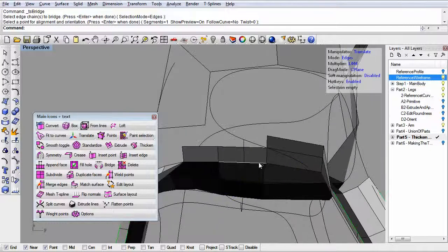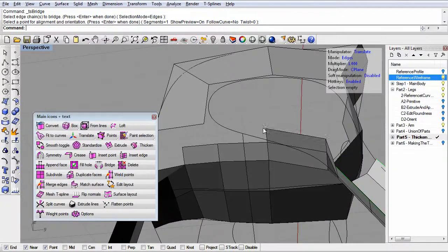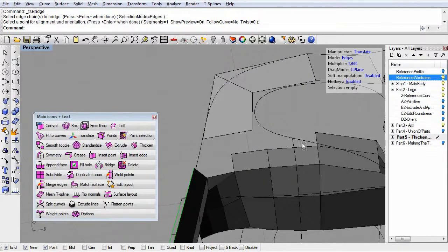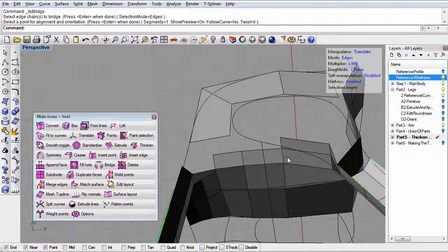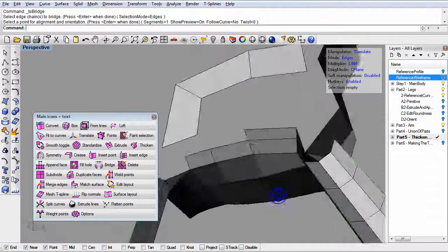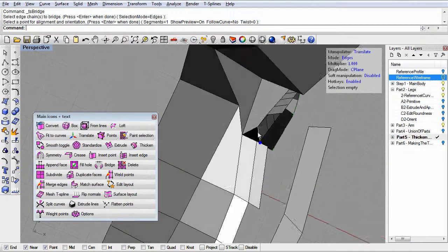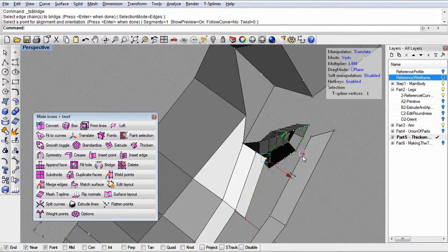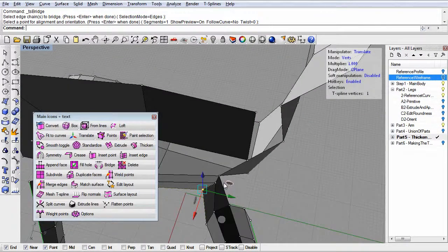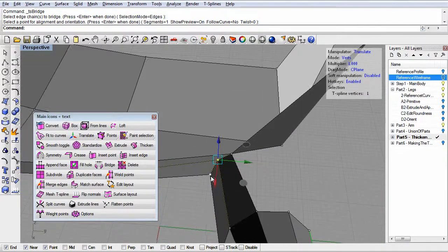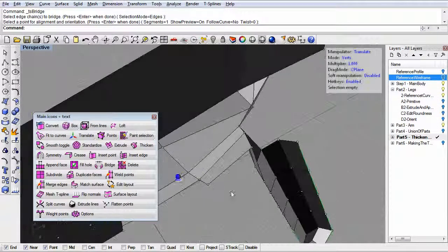What I'm kind of leaving exposed right here is this concave corner, and hopefully I'll be able to resolve that as I work over here later. Let's turn off the reference wireframe to get that out of the way. But let's see. Let me turn on my control points and just move this out a little bit so we can kind of see how that flow is going. You can see I'm not paying a lot of attention right now to what exactly my surface looks like. I'm mainly concerned with getting the topology right, and then I'll move those control points again later.